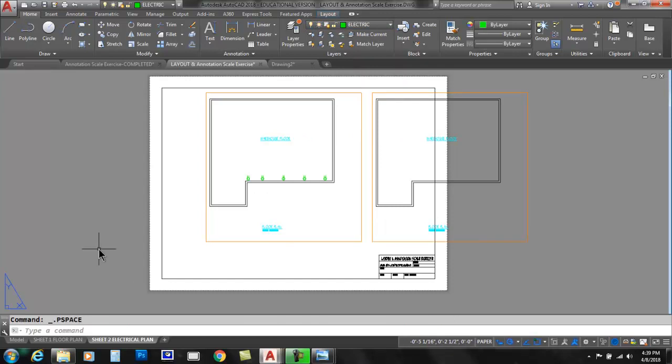And you may not realize this, but in a construction project, you would have multiple floor plans. Let's say even if there's just one story building, you'll have a floor plan that shows all the dimensions of the wall layouts and window and door locations. You'll have the same floor plan, but without all of that, but it'll show the electrical. A third floor plan that'll show the plumbing.